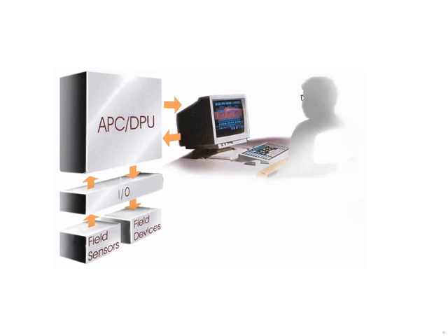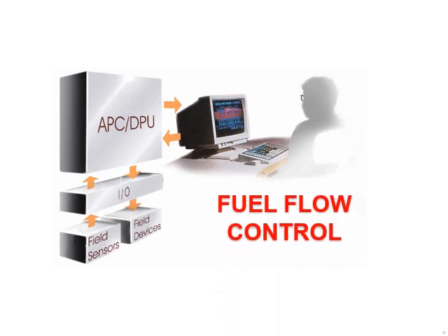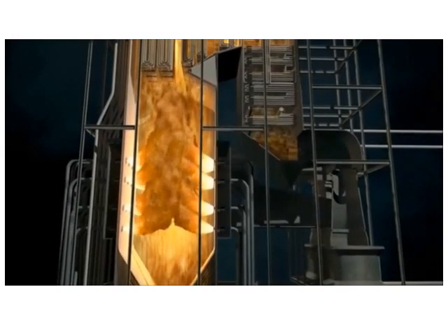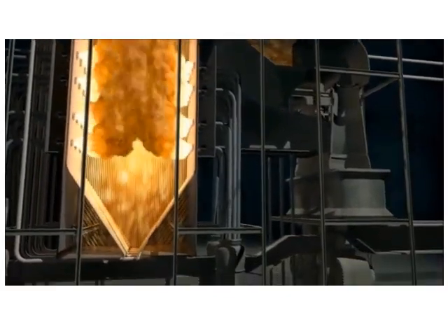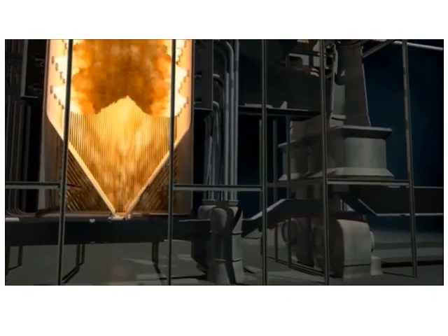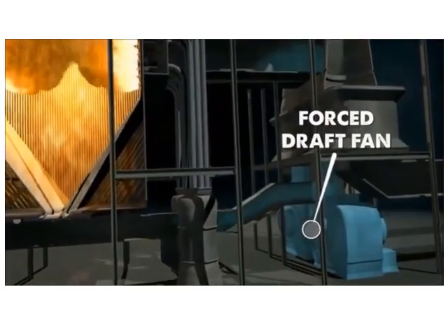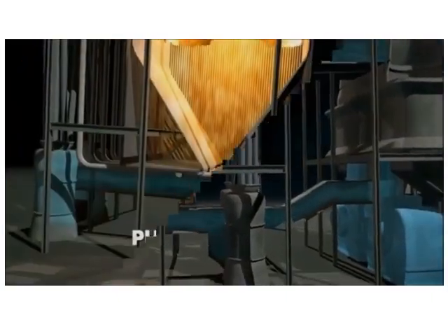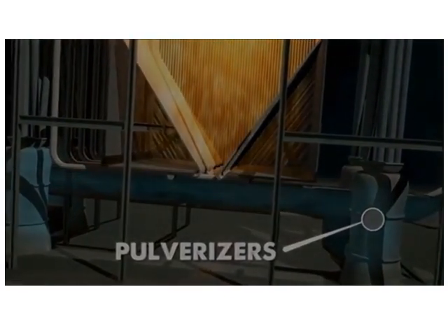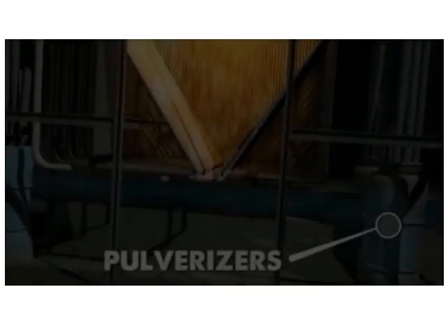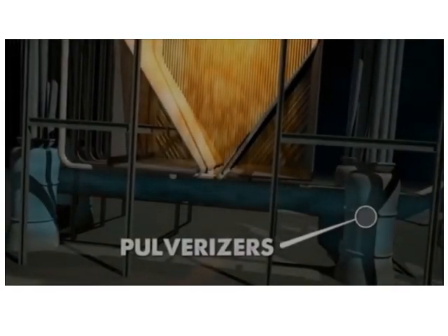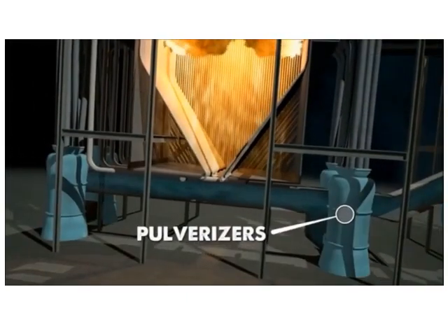Combustion control systems include air and fuel flow control. A combustion control system regulates the fuel and air input, or the firing rate, to the furnace in response to a load index. The demand for firing rate is, therefore, a demand for energy input in the system to match a withdrawal of energy at some point in the cycle.